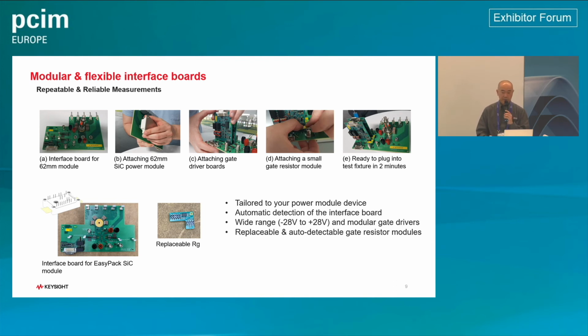And also, we have the standard gate driver board, which has a wide range, from minus 28 volts to 28 volts. And one thing, the bottom side of the slide shows the replaceable gate resistor module, which is very, very tiny. It has an SMD type gate resistor soldered on it, and you can just change this gate resistor module to a different value to change the gate resistor.